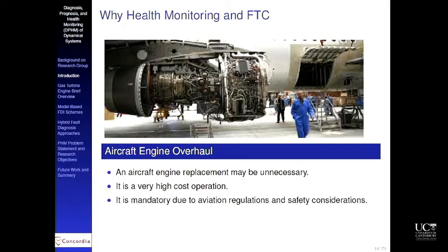So there is no need for you to maintain it after 10,000. Maybe I can go to 15,000. So you are going to spend money on maintenance when there was no need for that. On the other hand, if I'm, let's say, working in some polluted environment, then 10,000 is not good enough. Maybe I should do the maintenance at 5,000 kilometers. So this is the dilemma that we have.